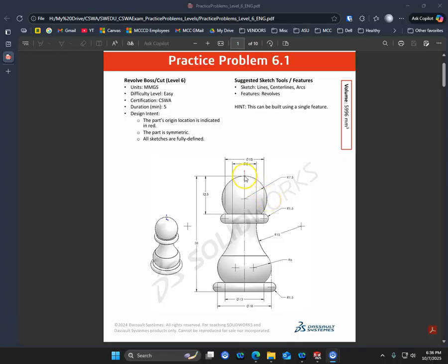So Revolve is going to have a center line. The problem with this center line is that the Revolve itself wants a closed contour. So it will see that geometry as open and want to convert it, which is not necessarily a bad thing. But if we start off with an object line, when we implement the feature, we just have to make sure that we select that as the axis of revolution. And based on this geometry, we really would only have this bottom edge and the vertical.